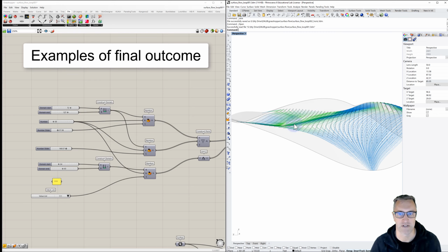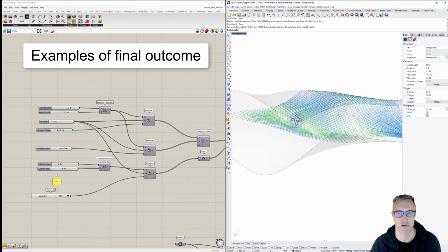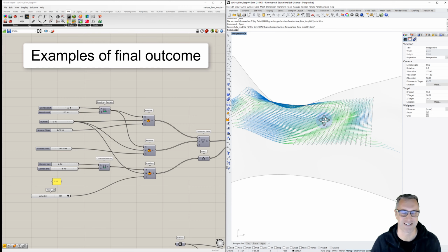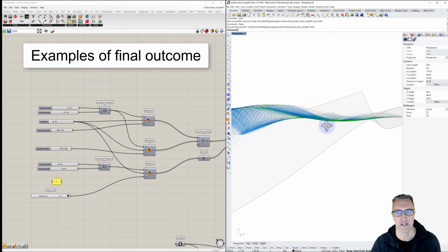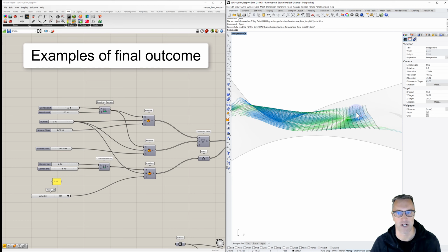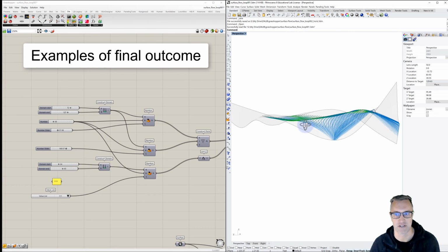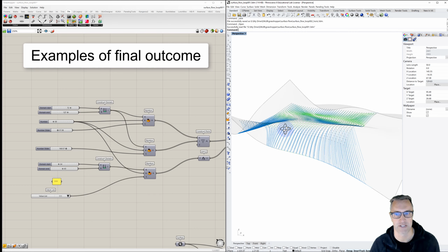The color gradient changes according to the slope, not the length of the line, which is a very easy thing to use the gradient to do. But what I'm actually doing is taking the continuous flow lines, splitting them up, analyzing the slope along that curve, and then color coding it. And so we can see, at least with this gradient, that where the slope is relatively low, it's green, and where the slope increases, it's blue. And I'll show you how to set these things up.